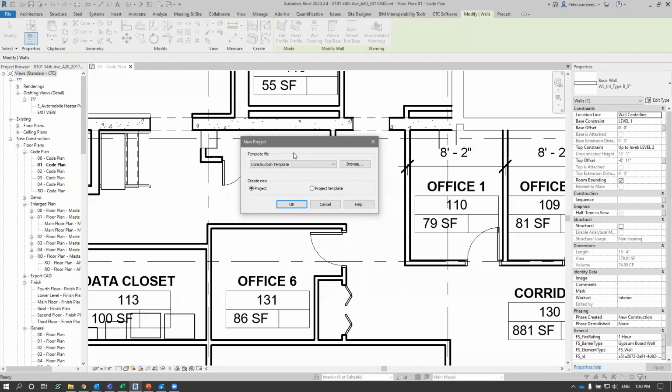Well, obviously, I can't actually have work sharing enabled in a template file. That's just not possible. And therefore, I can't have work sets enabled in those template files. I also can't have preloaded links in my template files. Again, something that's not the best, not the easiest thing moving forward.